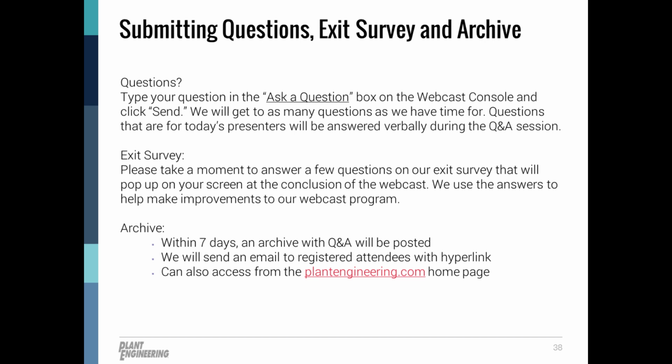We're not endorsing any products here, but we did see the advertisement for the Aegis grounding rings. Shaft grounding is a big thing with motors that utilize VFDs, because the bearings, if the shaft's not grounded, can take some damage, and it will cause fluting and blackening of the grease, and all of these things can lead to premature failures.